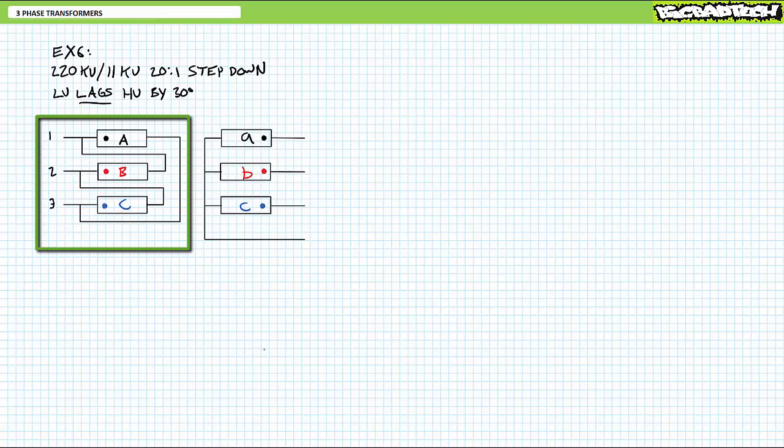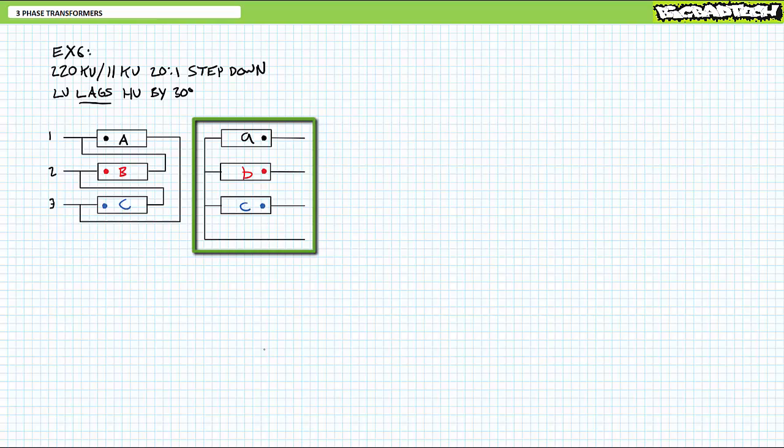Long story short, the high voltage side is a delta, so you get a capital D. The low voltage secondary appears to tie together all the non-polarity ends of the three windings and bring this out as a fourth neutral wire.